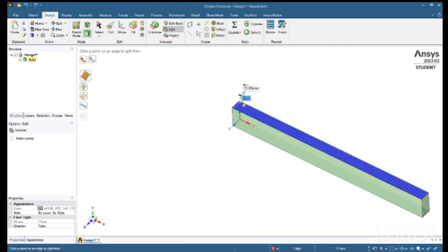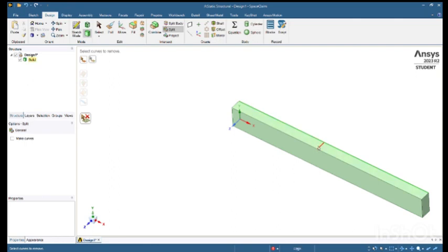So I am going here. I am able to drag this, and now I can enter here 900 mm, and then I will press enter. Now it has split this surface at 900 mm from this side.